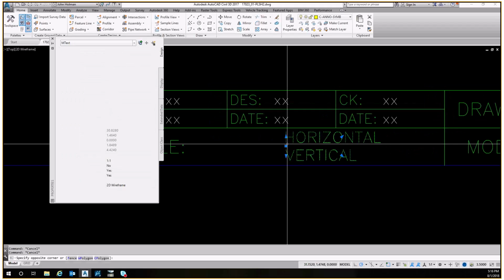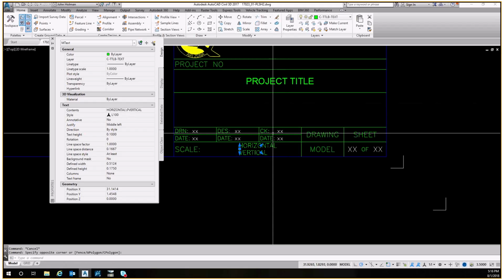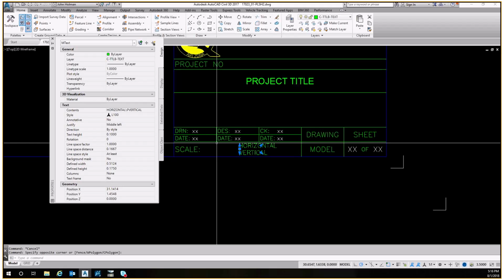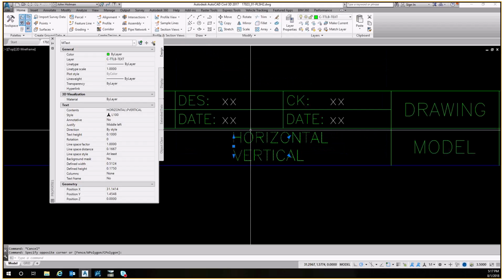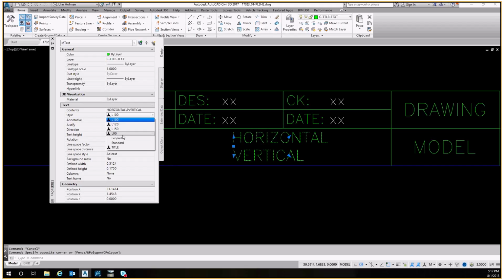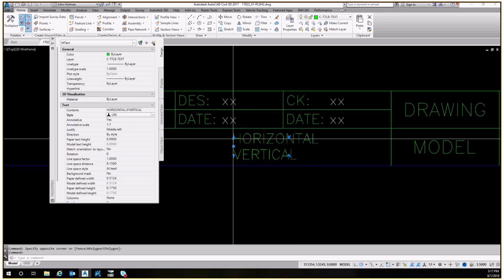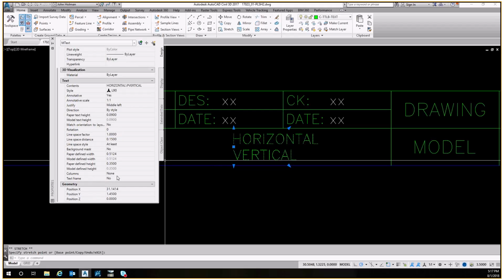So this horizontal and vertical, this is off. There are a couple of things that are off about this. All the text in this portion of the sheet template is either L90 or L120. The horizontal and vertical text is L100. There's not really a good reason for that, so I'm going to change that to L90, snap it to the bottom and top to make the Y direction, the Y position, good at 1.45.